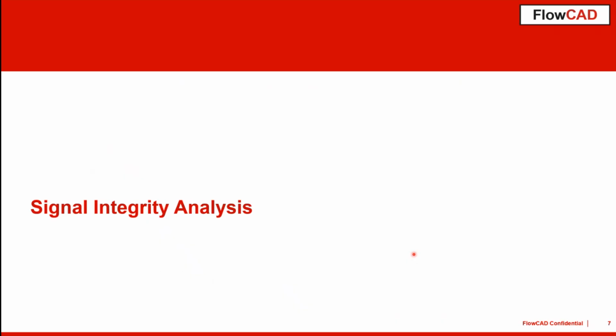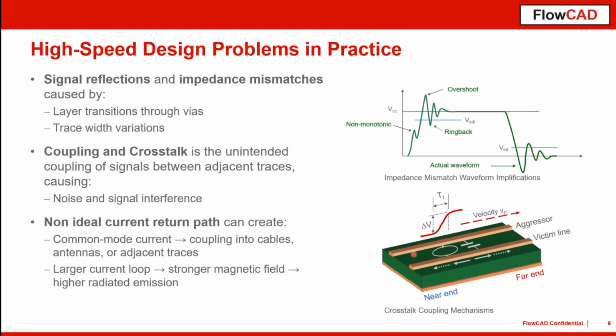So let's start with a signal integrity analysis that can be done with the in-design analysis. Typically, as you know, you have to achieve a quite smooth impedance profile on your PCBs to minimize signal reflections or other bad things. With the in-design analysis, you can directly see where you may have some impedance discontinuities that can cause ringing, reflections, and other things.